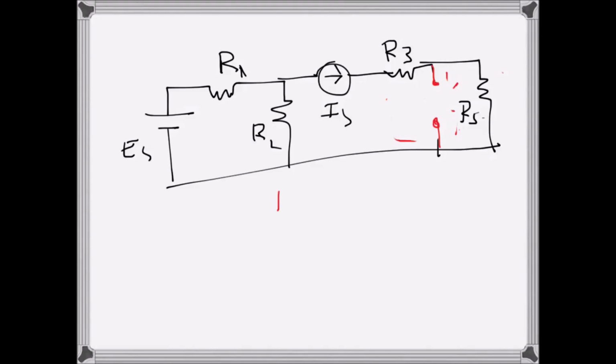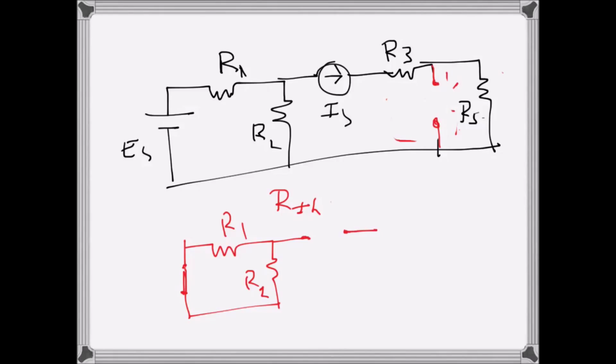Let's find R Thevenin first. In order to do that, we have to make the sources inactive. So of course the voltage source here is short circuited, with R4, R1, R2. This one is open here, the current source. This is R3, and R5 is here. So this is where I need to find the Thevenin's resistance.